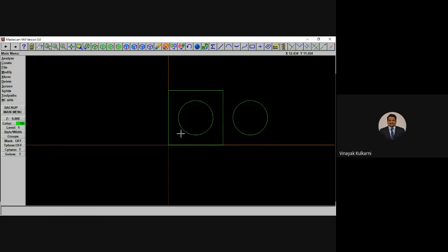So now I can draw a circle here, then trim, or directly fillet it. Now how to fillet that? Go to modify, fillet. My fillet radius is 7.5 mm. I'll press enter. Now when I do that, I want to trim, so you need to click yes to trim. I'll select this circle and this line. Now if you have seen, this part is gone. So how to recreate it, I will tell you in a later stage.